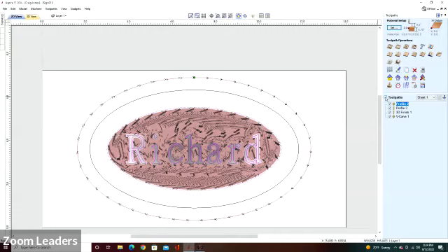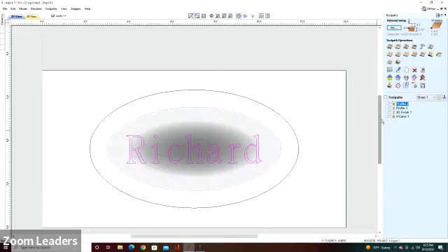Was that red line up there from your origin to the starting point or something? There was a diagonal red line on there. It went from here? Yes. So as Richard mentioned, it will tell you the path of your bit when it's not cutting as well. So if you happen to have a clamp or something on there, I broke my bit because I ignored that. I was taking some shortcuts. Expensive lesson. And then the bottom profile of the letters is just based on whether you get a V bit or a curve, and we'll do that right now.